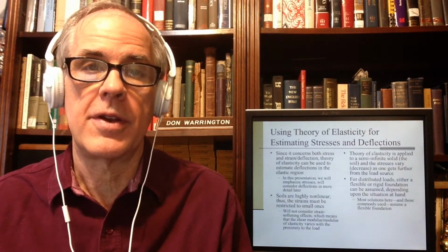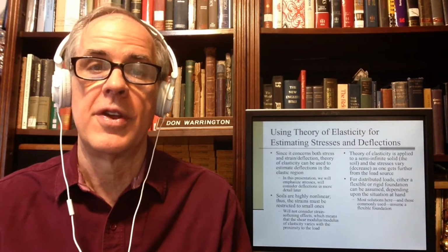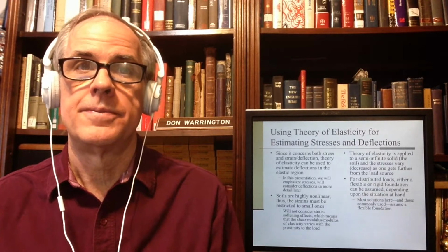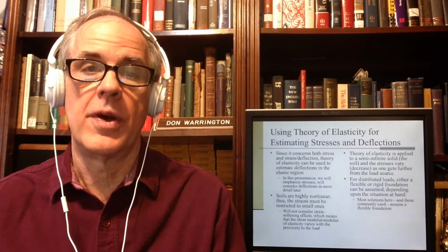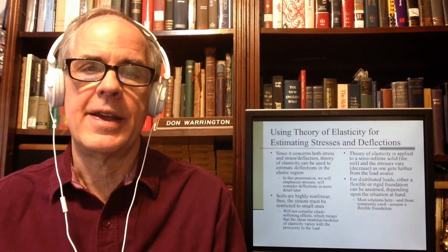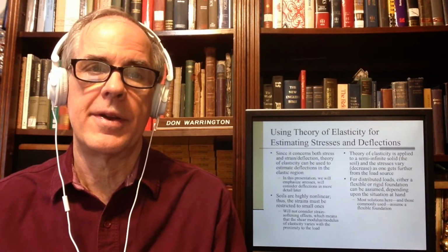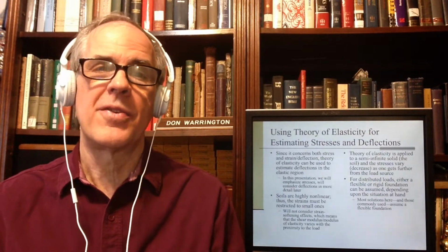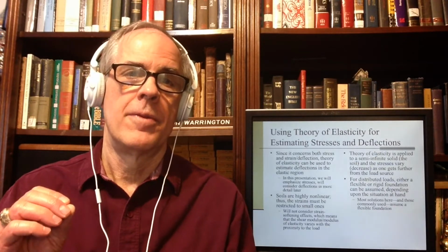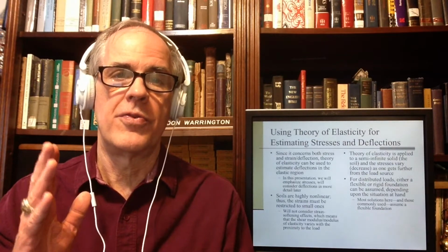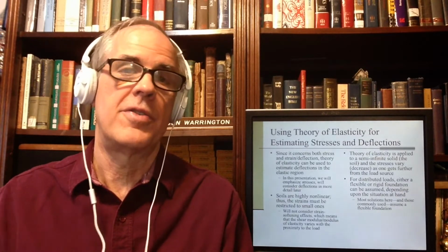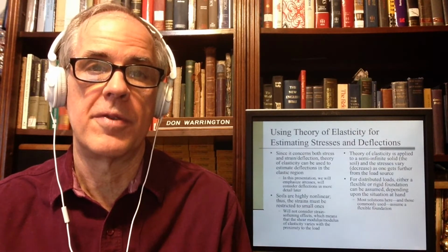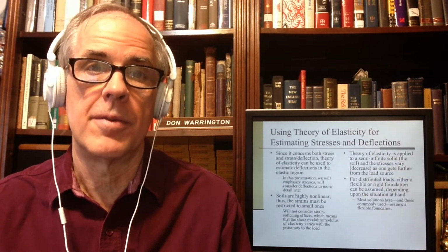You get different results, particularly when we talk about both stresses and deflections. Obviously, if you really want to nail this problem, you would use something else, because neither of these assumptions is really accurate. Some soils are very soft, and the foundations are, for all intents and purposes, rigid.